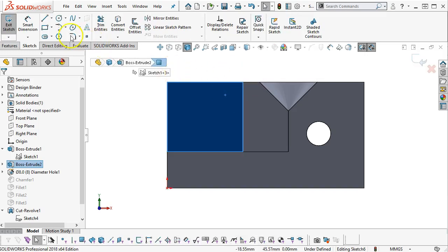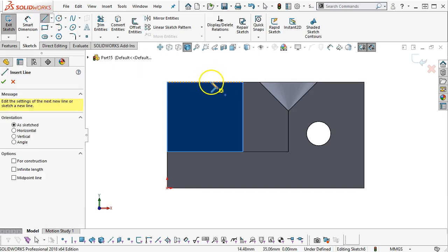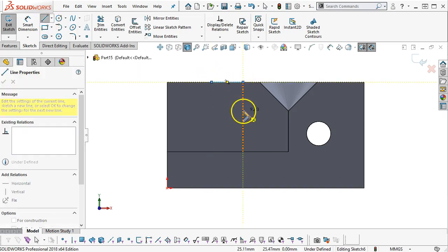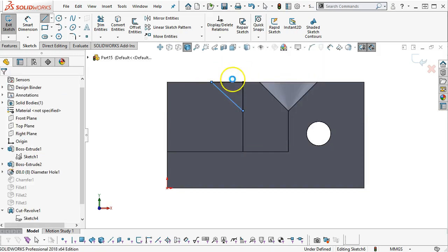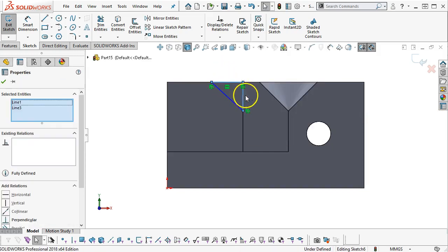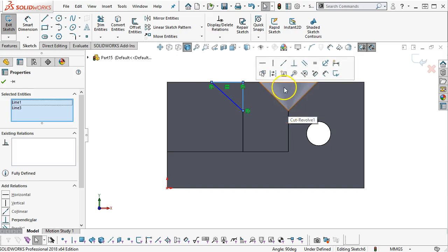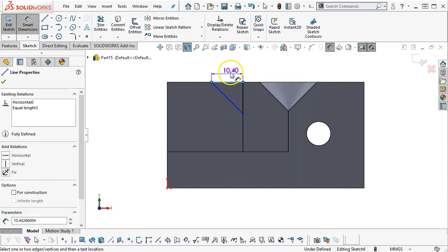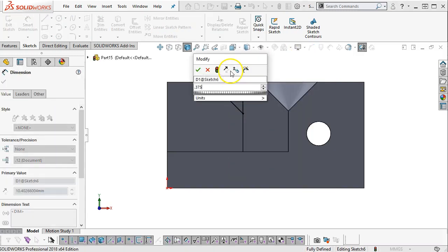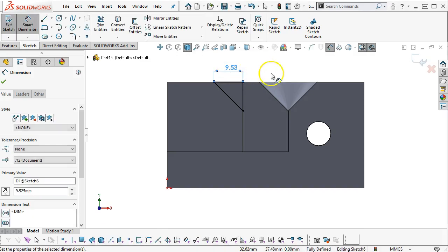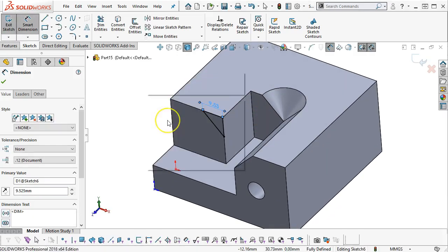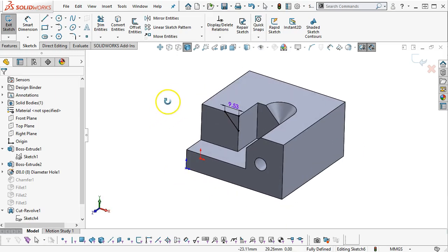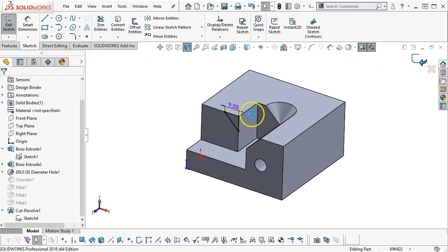And I did it again. So we'll have to move that out. All right, so the issue is going to be that a 375 radius 90-degree tool coming right to that edge is not going to have a lot of cutting action. And so it's going to be pretty bad in our geometry. So that being the case, going to have to get out of that again.